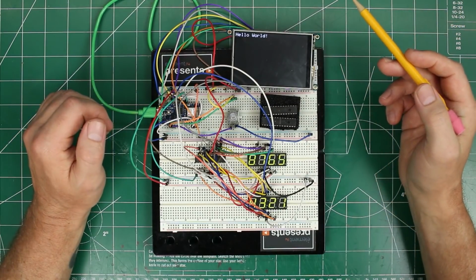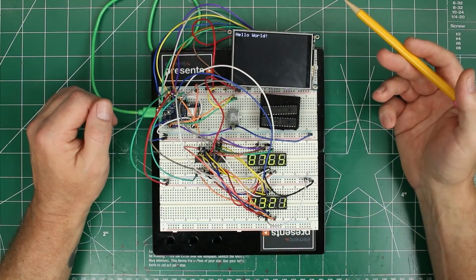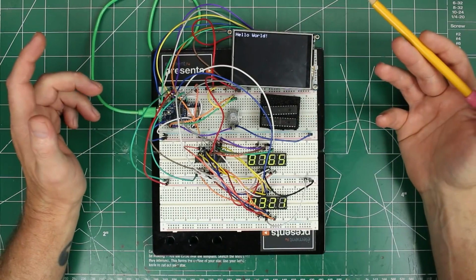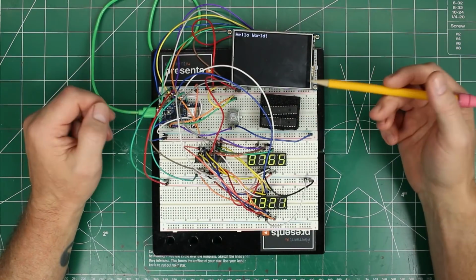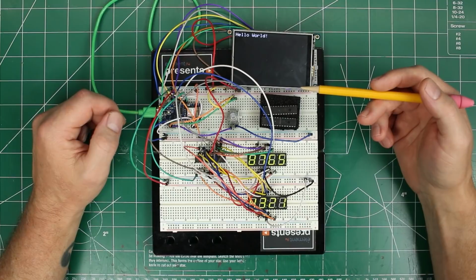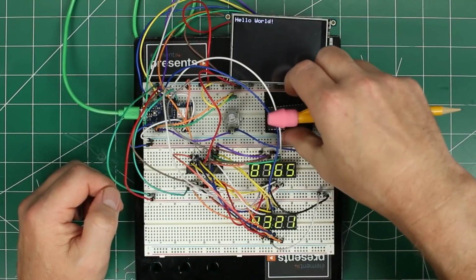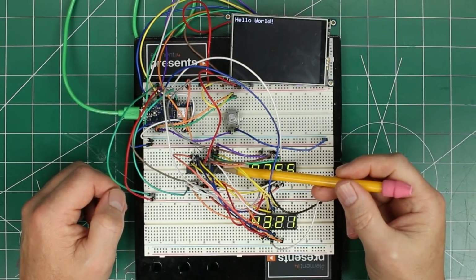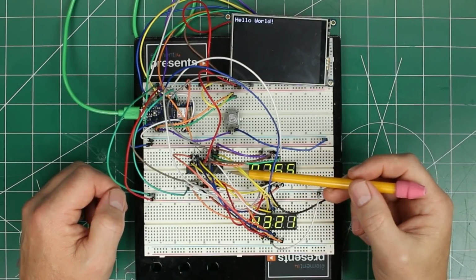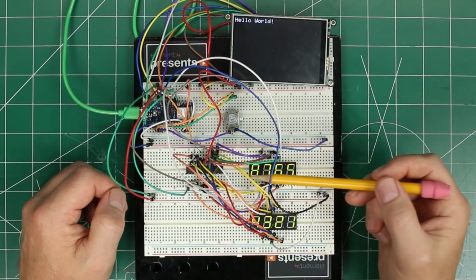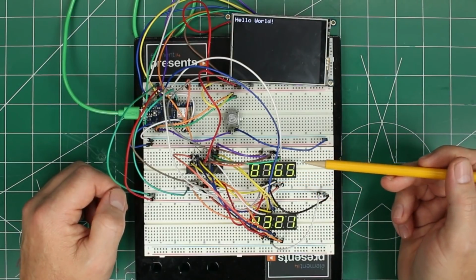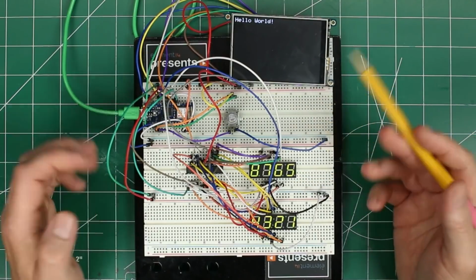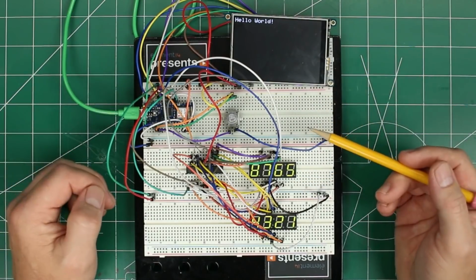In that same conversation, somebody piped in and said, why don't you just use the right IC in the first place? Well, my answer to that was because I didn't know about it. And that's what I meant when I said I wasn't using the right tools, or I didn't know about the right tool. So we got rid of these, and they told me about this IC, which is the MAX7221. It's a driver for 7-segment displays. It can drive 8-digit 7-segment displays, which is exactly what I needed. So I ordered a couple, and a few days later they showed up. Awesome.